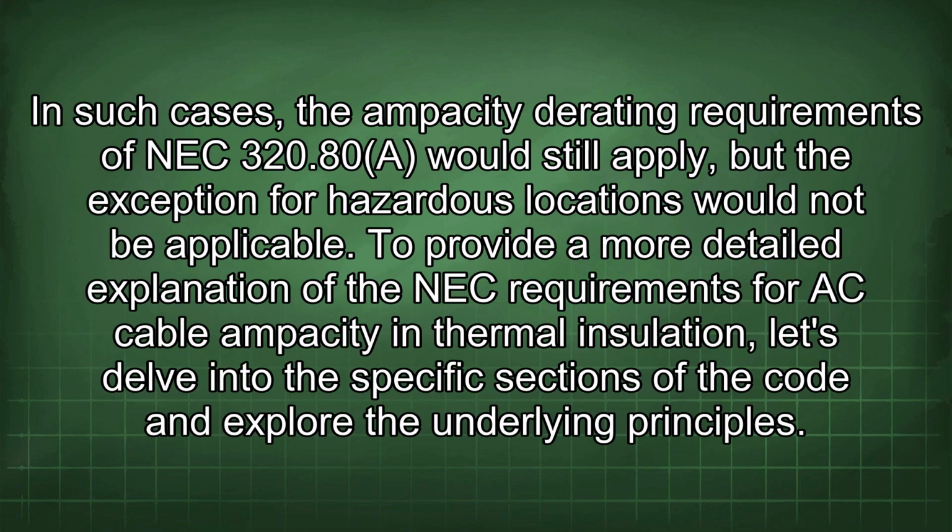In such cases, the ampacity derating requirements of NEC 320.80 would still apply, but the exception for hazardous locations would not be applicable. To provide a more detailed explanation of the NEC requirements for AC cable ampacity in thermal insulation, let's delve into the specific sections of the code and explore the underlying principles.